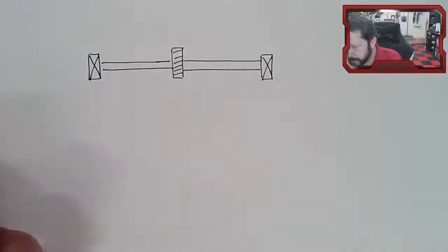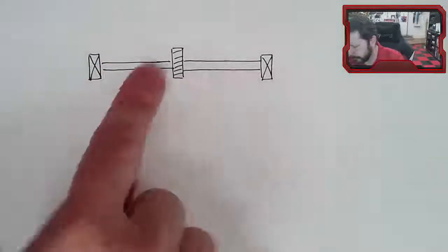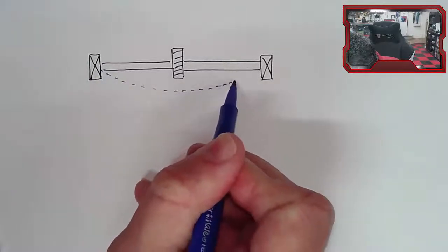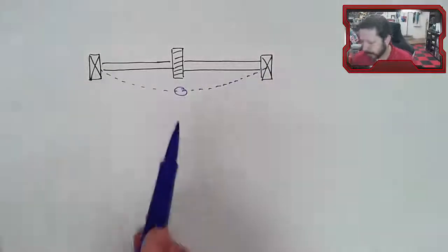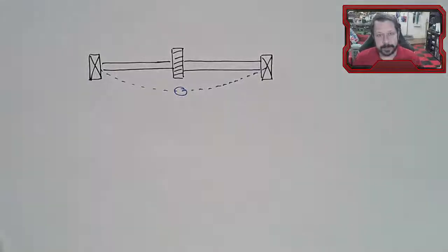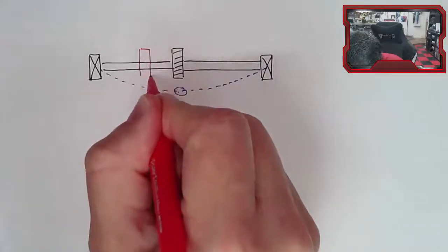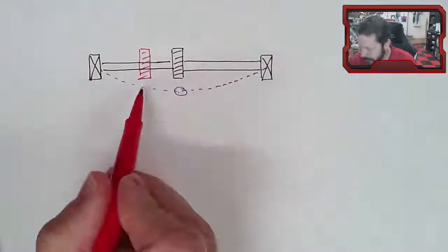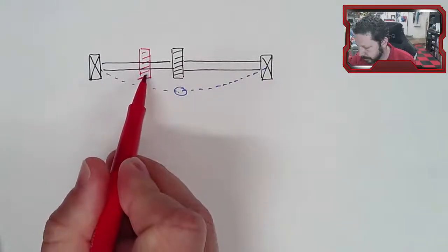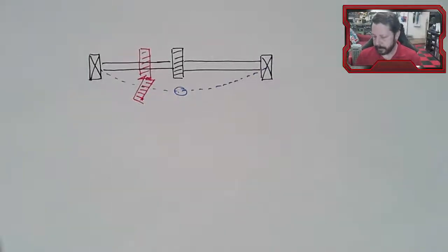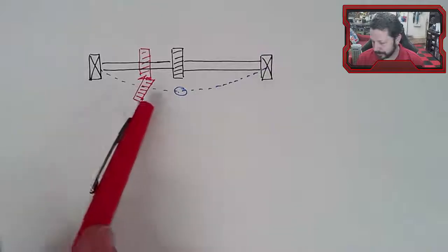When this thing deflects, you remember there is a radial force wanting to deflect the gear. But when it deflects, and I'm exaggerating the amount it's deflecting here, in this area, I don't have a slope. If I've got it right in the center of a simply supported shaft here, then the slope is 0. But if I had the gear offset, so let's say it's over here, not in the center, when the shaft deflects, now it's tilted. And so there's this effect of it not being in line anymore. It's got this slope to it.